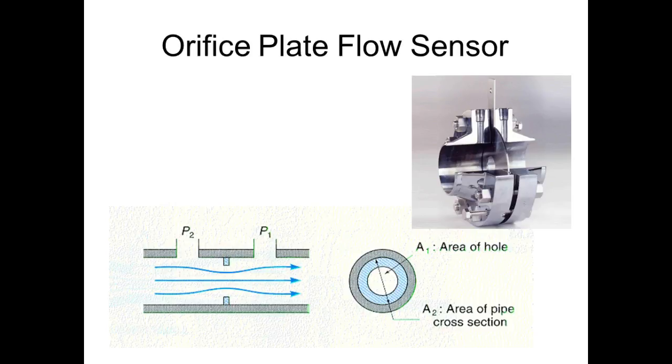So, but it's used, and you can see it basically just looks like a washer, right? Just stuck in here. And then these would be the two differential. Pretty small in that picture. That looks smaller compared to the. Yeah. Well, I don't know. I guess it's 4. Yeah, and but you can see the two pressure ports right here. So this would be your two pressure. One's on your high pressure side. One's on your low pressure side. And then you just measure what? The differential pressure. Are we okay?